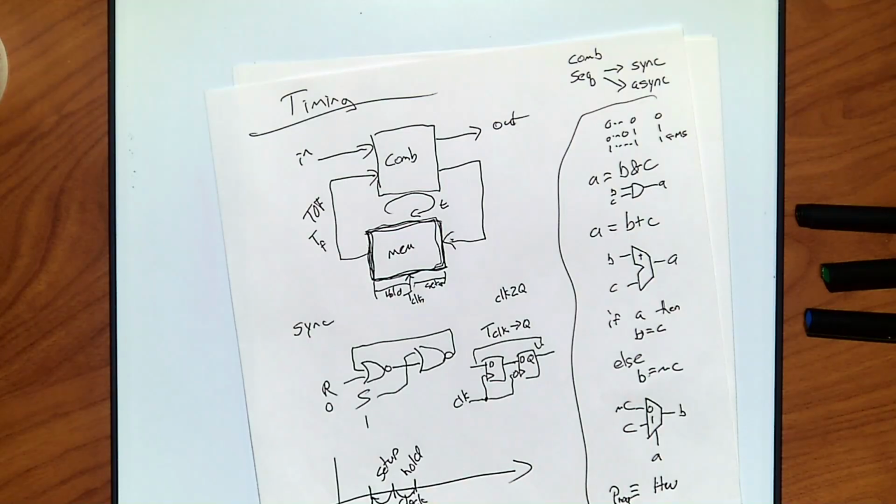So your real limit is going to be the RC constant of what the material is. This is why material choices and how you are building your circuit is so darn important. Because the time for the signal to go down the wire is heavily dependent on how that thing is laid out and its material properties.